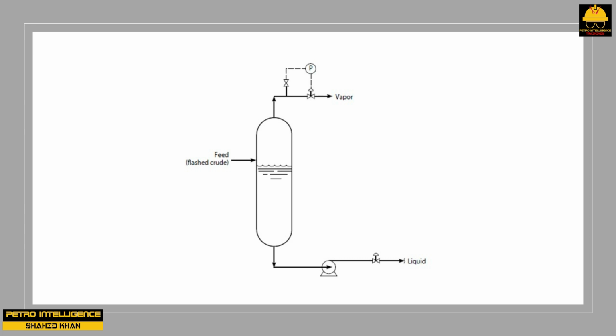As soon as the drum pressure is raised, the liquid composition in the drum is altered. The liquid composition at the vapor-liquid interface becomes lighter. The liquid formed at the vapor-liquid interface is still at its bubble point. When this lighter liquid works its way down to the suction of the pump, the beneficial effect achieved by raising the pressure in the drum is gone. The available steady-state NPSH will be exactly what it was before the drum pressure was raised.